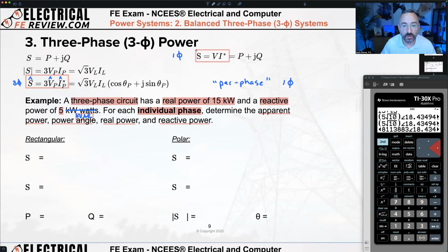This is phase voltage and phase current. Yeah, 3 times, said Daniel. So a great identity is that complex three-phase power equals 3 times your complex single-phase power. Or I can figure out the complex power in each phase of a balanced three-phase system by just dividing my three-phase complex power by 3. That's all there is to it.